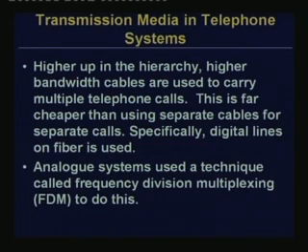So, if you remember the earlier figure we had, that we have this local exchange. Your particular subscriber would be connected to the local connection hut, maybe through a Cat3 cable. From that hut, a fat cable would usually run to the local exchange, and this fat cable in most cases today is still basically a collection of pairs of cables. So, they are just in one sheath. That is why that is a fat cable.